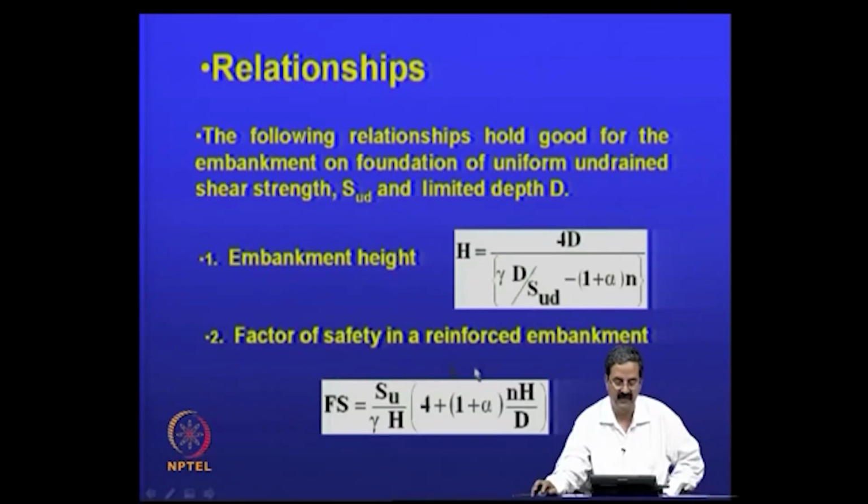And then the factor of safety of the reinforcement is also something one can calculate. It is a simple equilibrium equation, and one should remember these equations to solve some of these problems. Again, the higher the embankment, the factor of safety can be calculated using this simple expression. It is nothing but the driving forces to resisting forces, just a horizontal equilibrium.